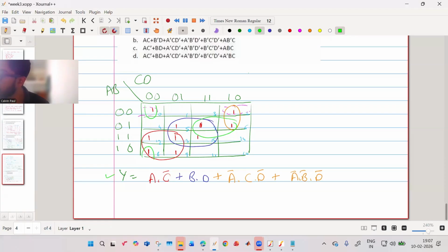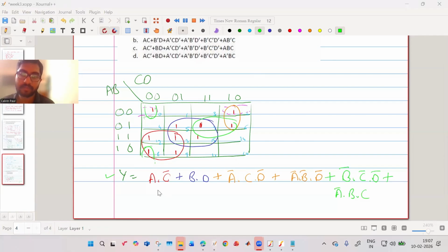So what you do, you add plus, what is the first linkage? That is equal to B bar and C bar and D bar, plus for your next linkage, it is A bar and B and C. Okay. If you do this, then you can be assured that you don't have any hazard. Okay. You're overcoming the hazards.